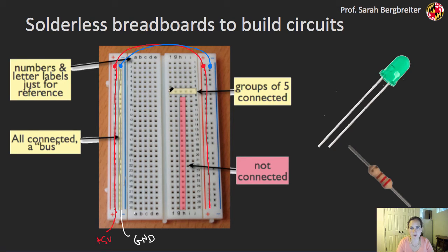And everything else in between these lines right here, kind of depicted horizontally, but often I can think of them as vertical lines. These lines are all connected to each other, but these big columns are not going to be connected to each other. So all of these pins are connected, but those aren't connected to the next row down, if that makes sense. And then obviously I can use this breadboard to plug in a variety of discrete components, maybe an LED, maybe some resistors or capacitors, and build a circuit that I can interface to my Arduino, connect ultimately sensors, or connect my Arduino up to actuators that would form our full mechatronic system.